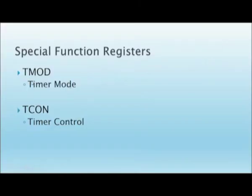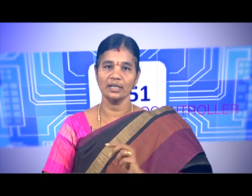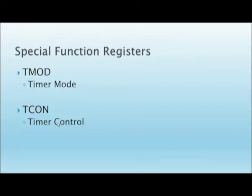By coding itself we can control it. It is an 8-bit format. Another one is TCON, which is the timer control. Based on the name you can understand it is used to control the timer function. Controlling the timer function means when to start, when to stop, and this kind of additional information. Along with that, whether the timer runs on T0 or T1 is set in the TCON. So, for any kind of timer application we have to activate the TMOD and TCON registers.